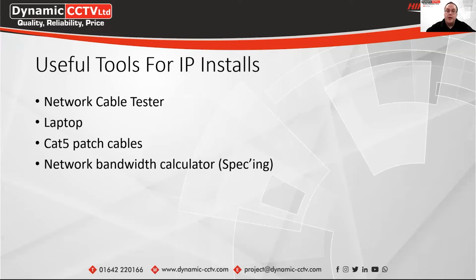Now, before we get on to the live demo of some of the systems, I just wanted to make some recommendations for useful tools for installs, especially for IP equipment. Always use network cable testers. Even myself, I've made plenty of cables. The one cable that you don't use on a cable tester is the one where there's a core missing or it hasn't crimped properly, and by the time you've wired it in, you then take it back out and redo the actual ends on the cable, whereas testing it before with a network cable tester saves that extra time further down the line.